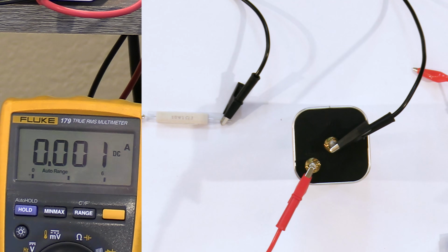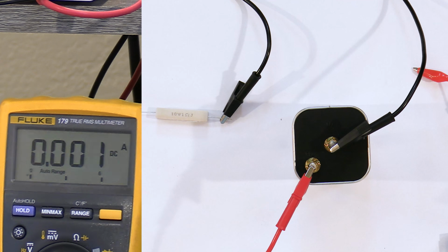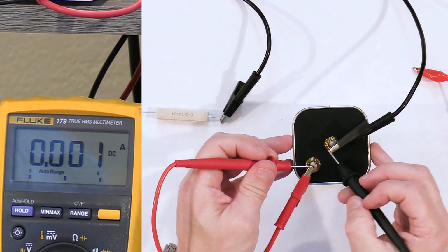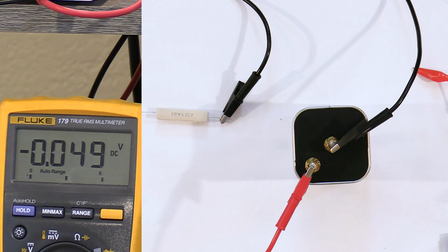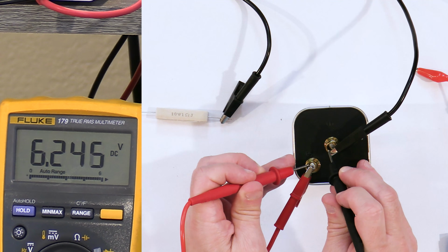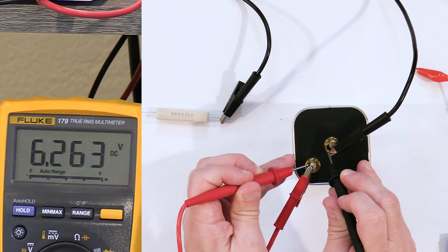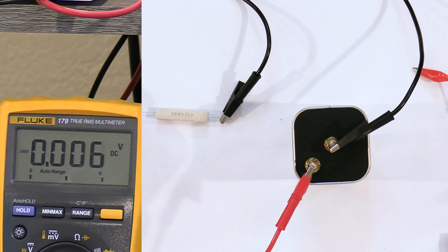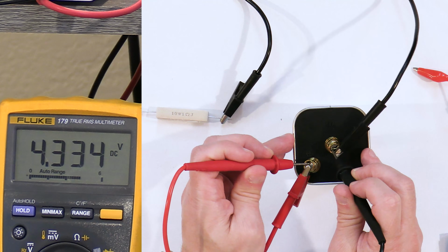And now what I'm going to do is, while this thing is in operation, actually let me disconnect it. While there is no current flowing, what is the voltage across here? We've got to switch it back to voltage. What is the open circuit voltage when nothing has happened? Notice it's already a little bit drained because I've been using it a lot to supply a lot of current, but it's at 6.2 volts. But when I'm asking it to supply the current, I'm getting about 3 amps flowing through that. What is the voltage right now? The voltage is not 6 volts anymore.